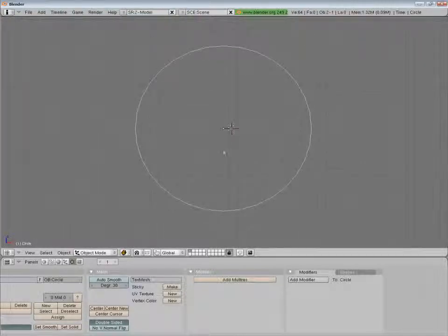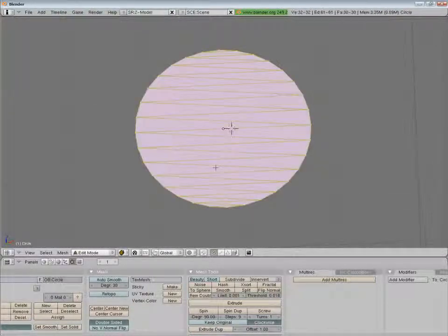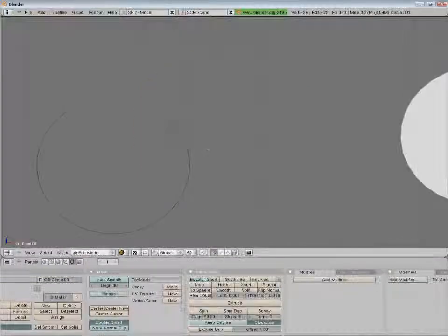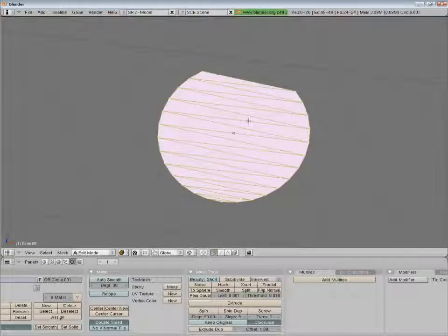If you want to make a face for many vertices, or in other words if you want to fill, select all vertices and then press Shift F. Make sure the object is not open, as in this case we select all and press Shift F and nothing happens. Now if we join the 2 points and close the object and then select all and press Shift F, we now have filled points.